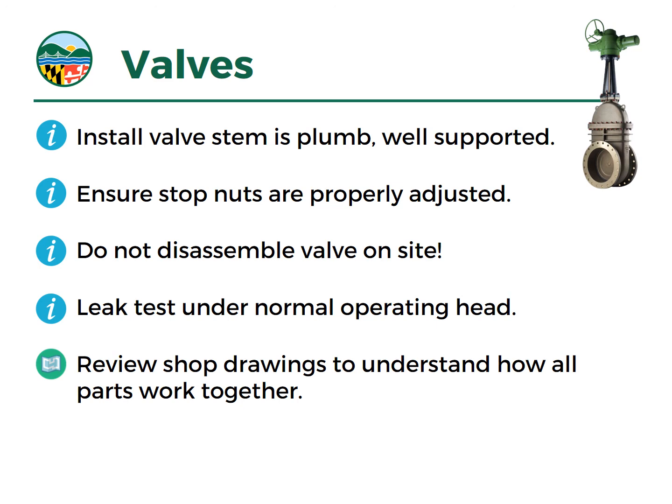I've had a few cases where the contractor, for whatever reason, disassembled the valve on site. They didn't want to lower it down into the shaft or into the riser structure in one piece. It was calibrated at the factory and in good condition. It never got reassembled with the same factory tolerances, and it leaked like crazy. It's going to have to be replaced, and my understanding is the project cost is in the many hundreds of thousands of dollars for this one particular project, all because the contractor cut some corners.